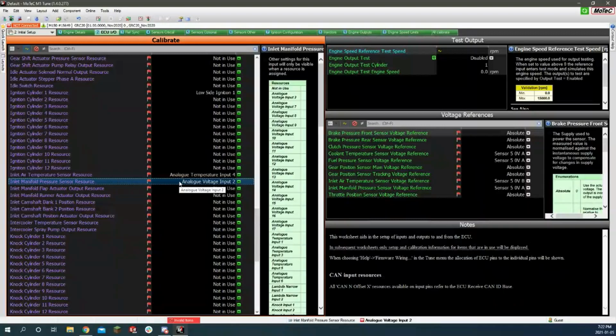As you increase the throttle, so as you step on the gas pedal, it opens up the throttle plate and puts more air into the plenum. It allows it to flow in faster, which creates a greater pressure in the plenum. Typically, the pressure in the plenum will go down at idle, or when you close the throttle at a reasonably high RPM, it'll be down maybe 20, 30 kPa.